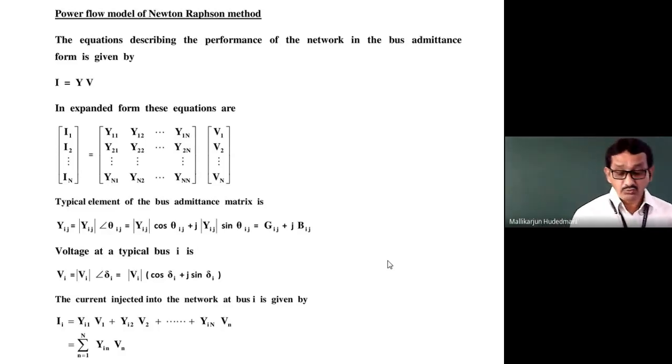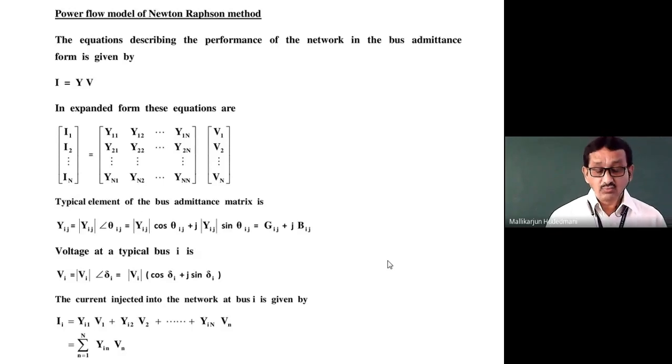In that perspective, we began the study of load flow methods using one of the best and easier methods, Gauss-Seidel, in the earlier module. And we could justify it's a simple method, but it is a little lengthier. In line with that, we witnessed how the complex nonlinear equations which result when we connect P, Q, V and delta of a given power system are solved using a numerical solution, the GS method.